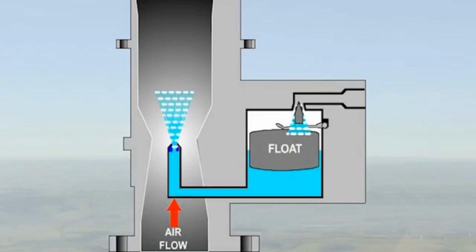The simplest solution to the problem of maintaining the correct air-fuel ratio in response to throttle settings at all operating altitudes is the float chamber carburetor. The float chamber carburetor employs two basic principles. They are the U-tube principle and the Venturi principle.